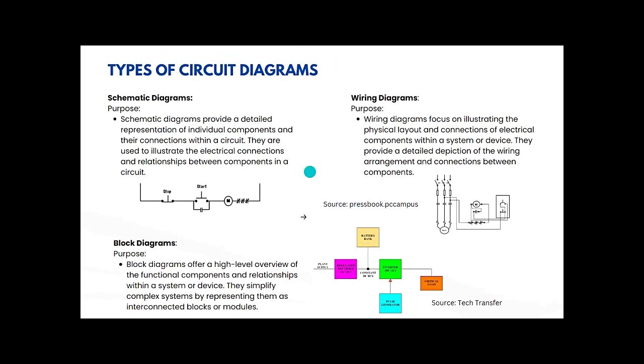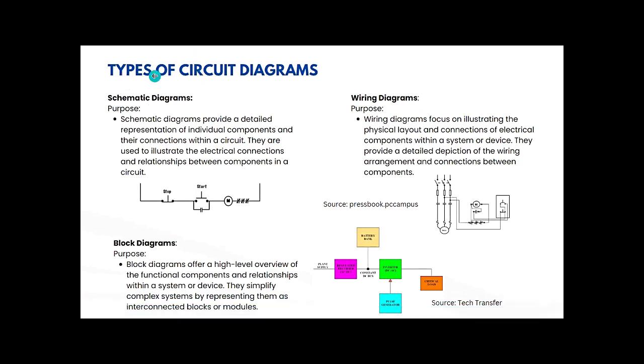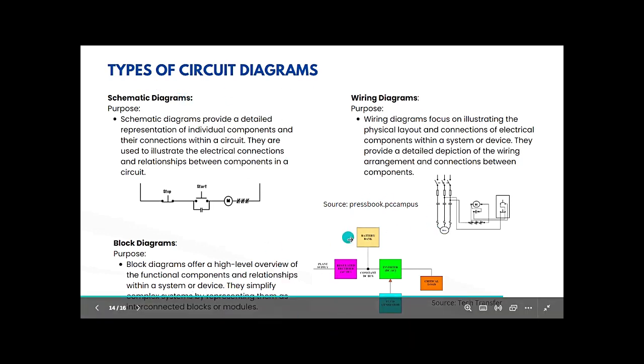For an inverter, there are different stages like the power stage, the oscillator circuit, the amplifying circuit, the output circuit, the low battery cutoff circuit, the high current circuit, all those stuff like that. So instead of drawing or designing these with a schematic diagram, which would make it look like a complex diagram, you can use a block diagram to define or design the circuit.